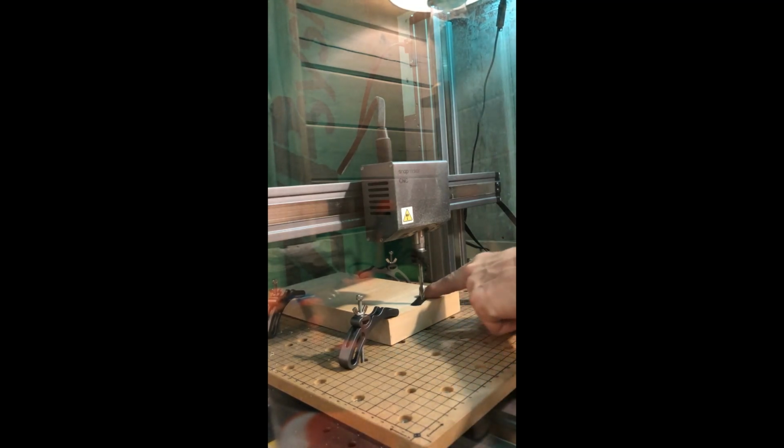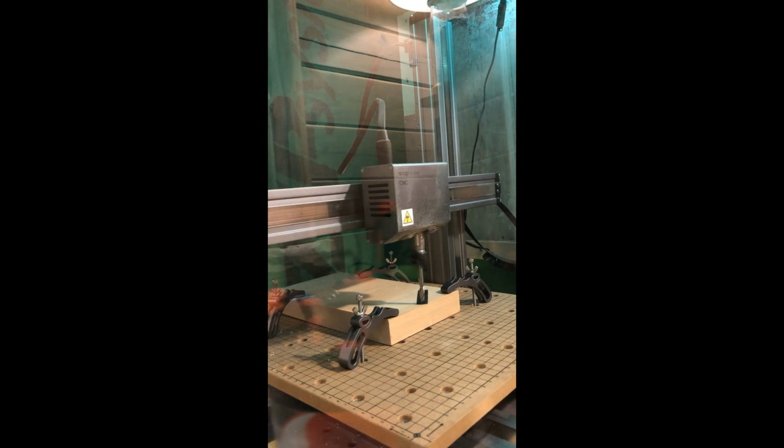Make sure you don't push on your plate, because you can move your table up and down in the east and the west, or I'm sorry, in the Y direction. You definitely don't want to be leaning on here when you're doing any of this. So make sure you're not leaning on here, you're not pushing. Put your feeler gauge on there, or whatever you're going to use to set the height. And we're going to lower this down so it's just snug. When we get close, we'll break it down to 0.1. And I want to be able to feel that on there.